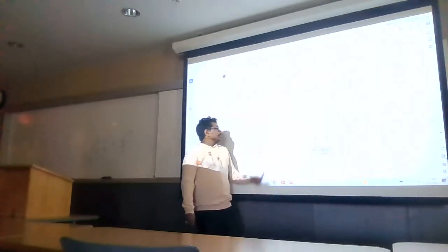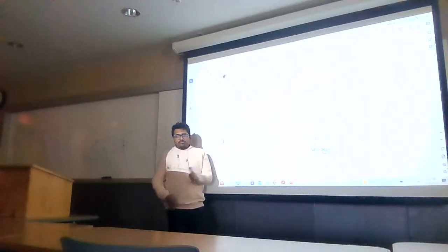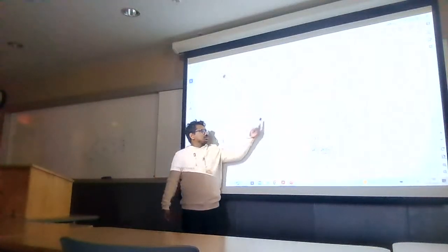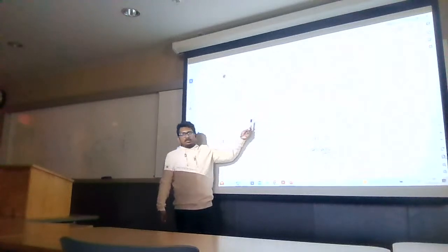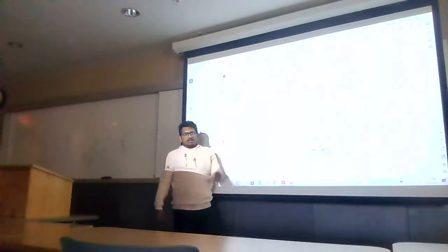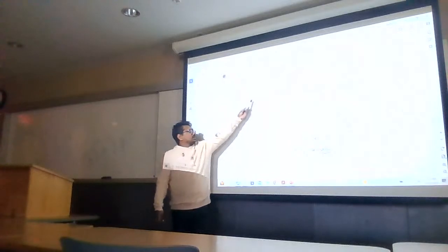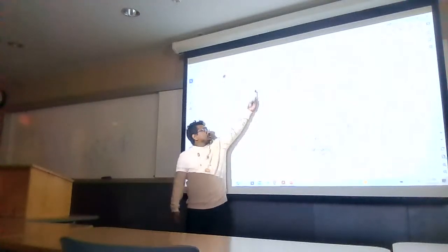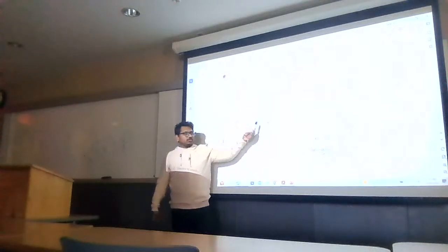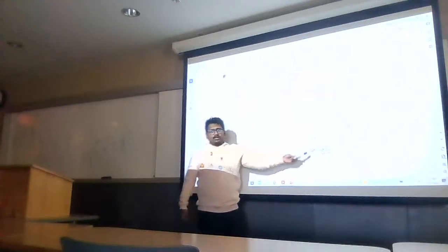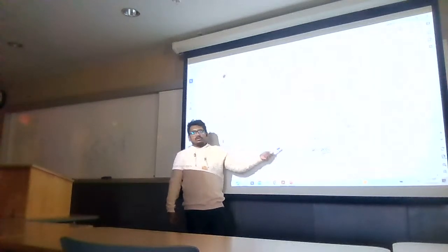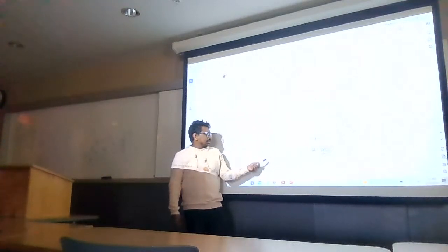It means the gain of the circuit only depends on these two resistances. Obviously with temperature change the resistances will change, and here also the same effect: this one changes its property, that one also changes, and they cancel each other. In this way there is no process dependency, and the voltage gain is more stable.